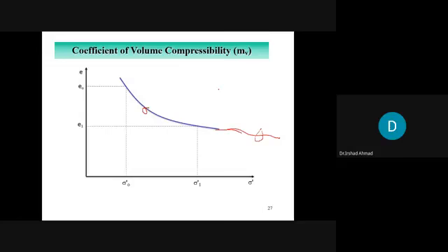So actually, what stress range you would consider depends upon the problem at hand. For example, you got this curve from the laboratory. Sigma naught prime is the stress at the site, ठीक है ना, at a certain point, and you find E naught. Now, because of the building, the current stress would increase from sigma naught by delta sigma.